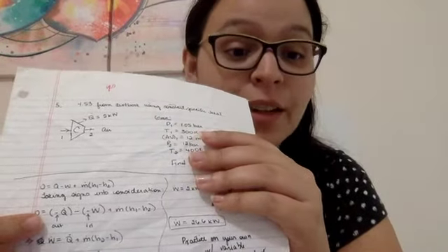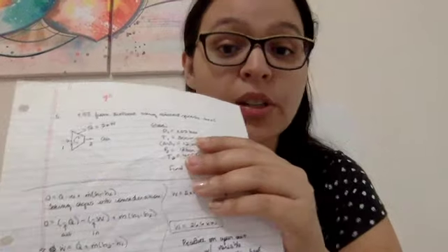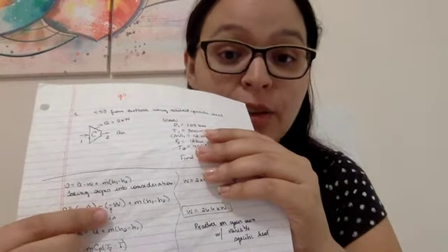Now we have to take the signs into consideration for the direction of Q and W. So this is the tricky part for some students, right? We have that 0. For Q out, it's negative. And then we have the negative from the equation. And then work in is negative. Okay, we need to include those signs. Otherwise, the result for work will be wrong. Okay? And then we have plus m dot h1 minus h2, in minus out. Okay? And then we end up with the equation for power, which is Q dot plus whatever.